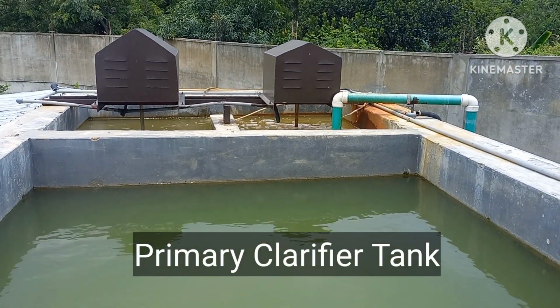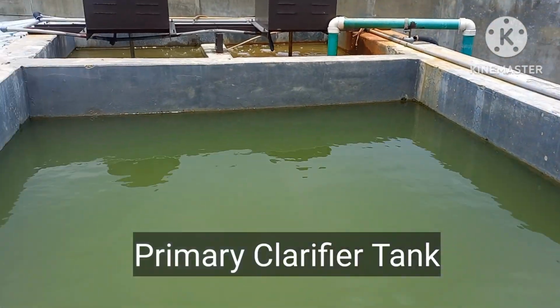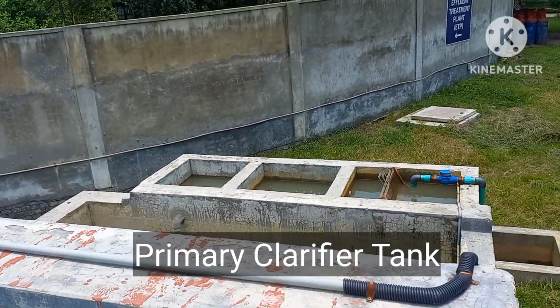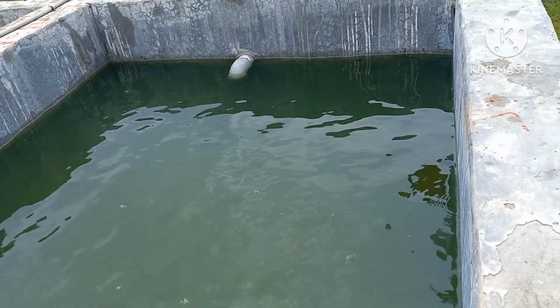The heavier suspended solids settle in the clarifier due to the calm conditions provided in the clarification zone. The settled solids are swept to the center well provided for collection of sludge.